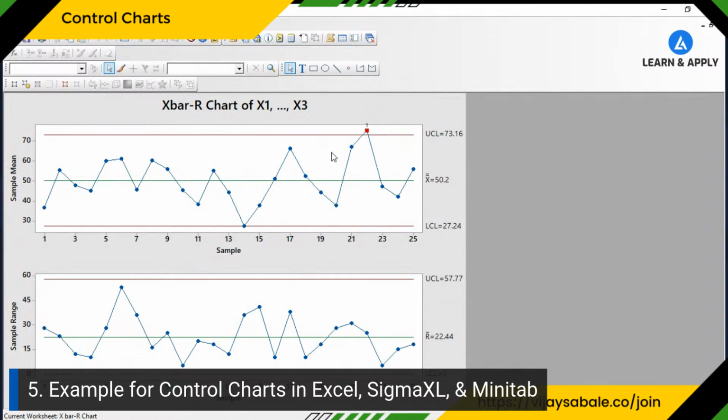Now again, there is a common mistake that people are making during the interpretation of this. People are directly going for this X bar chart, right? So that should not be. We must understand the range chart first. We must see whether the range is in control. If everything is in control, then and only then we need to go for the X bar chart. So that is a basic mistake again people are making. So please check. Now, if you look at the range chart, we can see, yes, all the points are in control. So we can look at the X bar chart.